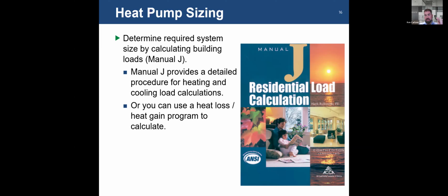When you go to those dual fuel systems, that's a completely different switchover, because oftentimes the heat pump sits on top of the furnace. The furnace would actually end up heating the refrigerant, right? So in cases like that, it's a hard switchover. The heat pump runs down to a certain ambient condition that you would choose, and then below that, you would shut off the heat pump, and the furnace would take over.